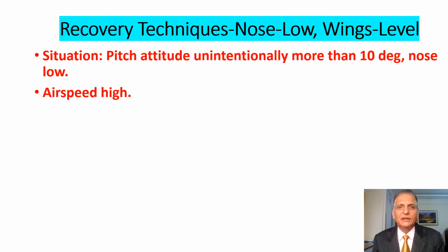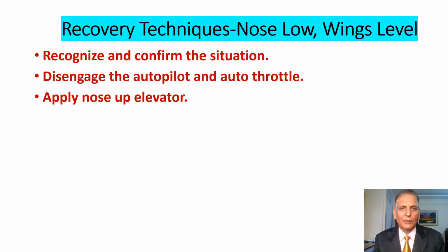Now we shall discuss recovery techniques: nose low, wings level, but airspeed is high. Situation: pitch attitude unintentionally more than 10 degrees nose low and airspeed high. Recovery technique: recognize and confirm the situation, disengage the autopilot and auto throttle, apply nose up elevator.